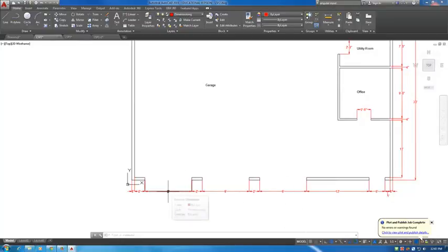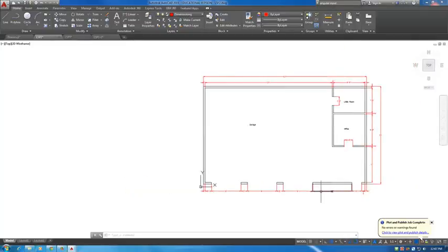If you have any larger vehicles, say larger pickup trucks, three-quarter-ton pickups with larger fold-out mirrors, or larger vans, you're going to want a 9-foot door. It may be hard to squeeze those vehicles into an 8-foot door. Everything I've built, I put 9-foot doors in. Keep it easy, keep your cars not scratched. Again, just some reference ideas. A lot of this information is available via Google. You can Google basic architectural design or how to design a garage. You don't have to rely on me.